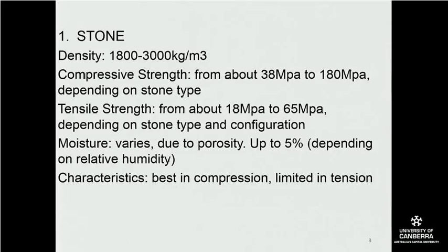Also, it has a similar kind of strength to concrete, similar density to concrete. The compressive strength ranges from about 38 megapascals to 180 megapascals. So the weaker stones are actually about the same compressive strength as timber.